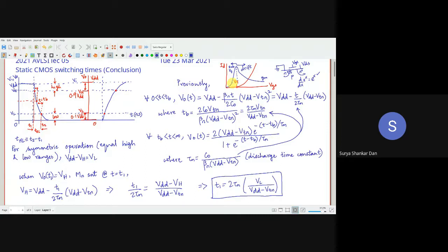The only thing is that the currents will be very small. If you are not concerned about very high current in a particular application, you should always try to go for subthreshold designs. Anyway, GM is exponential, so that's why it is very sharp. And after VT is reached, what will be the GM?